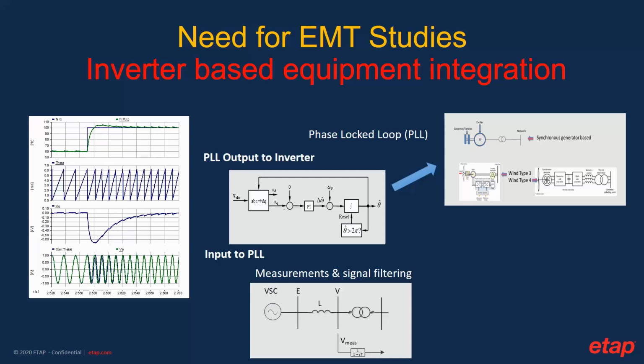radians. Now, this instantaneous angle measurement, remember, is not a phase angle that we deal with in phasor simulations. This is the instantaneous angle of the voltage. This angle is a critical input to power electronic controllers. Wind farm or solar inverter controls depend on accurately estimating the angle of the voltage at its connected point to do proper protection and control actions.